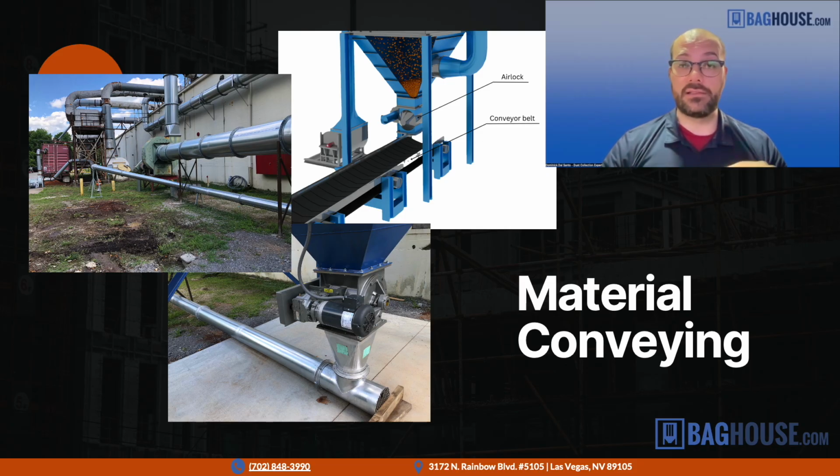But these systems, for all intents and purposes, function the same way as normal baghouses. Sometimes as well, when you have lots of screw conveyors, these, depending on how they're used, usually need some kind of dust collector hooked up to them to pull the air through because they make a lot of dust. So your screw conveyors, your bucket elevators, your discharge points between the belts, if you have a lot of belt conveyors dropping one to another, all of these spots, you usually need some sort of dust collection at that source in order to avoid having fugitive dust emissions coming up. So looking at your material conveying is often where a lot of the dust collection needs in your plants are going to be.